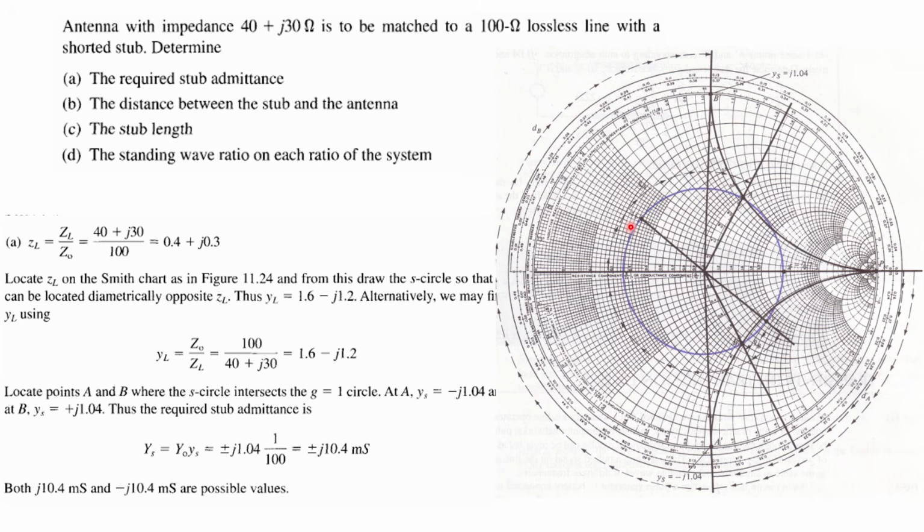Now what to do? Find the origin. First we find your location, that is ZL, this point we have already got. Now the origin. Where is the origin? Always remember the origin is at 1 comma 0. So this is your origin. Now connect your ZL point to the origin, right, and extend it.